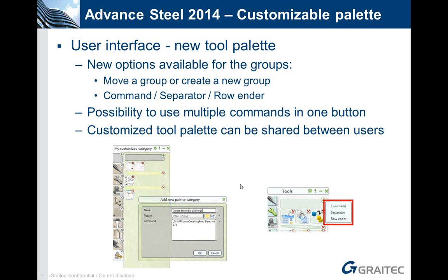Once this is done, once you customize your tool palette, this is saving a specific file on your hard disk, an XML file, and you can give this file to another user so that he can get the same customized tool palette as you did on your side.